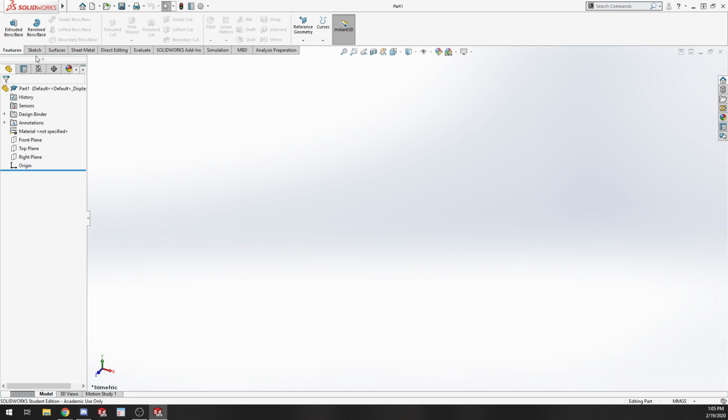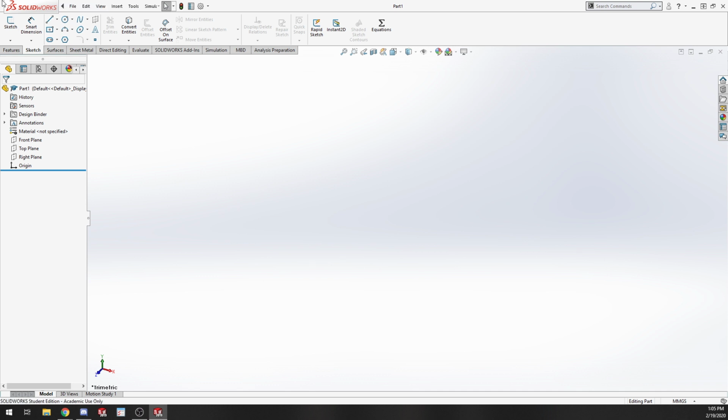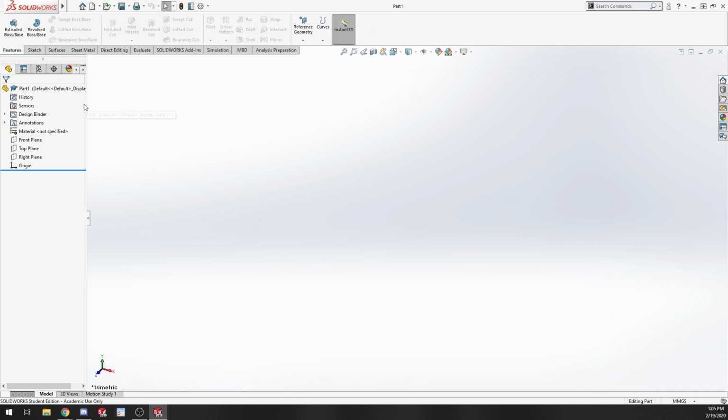And to go through just a theoretical difference between all of them. With a sweep feature, we can only have one kind of cross section, so that could be a circle, an ellipse, a square, a rectangle, but basically you can't make a circle become a square, you can't make a square become a circle, you can't add or remove segments. With a loft, you can do that. You can go circle to square, like we were doing with the fan duct last week.